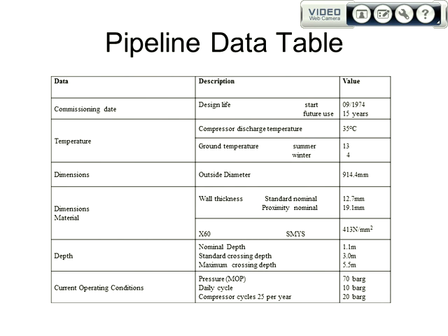Now, that's one of the bits of information I haven't given you that you need to look at. When you look at the design calculations for the pipeline, it will tell you to use minimum wall, not standard wall. So you're going to have to find out what the minimum wall is. What I suggest you do is assume that the pipeline material was supplied to API 5L. You need to look on the internet and get API 5L and then find what the manufacturing tolerances are for a pipeline of that size.